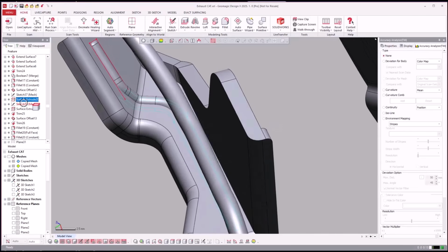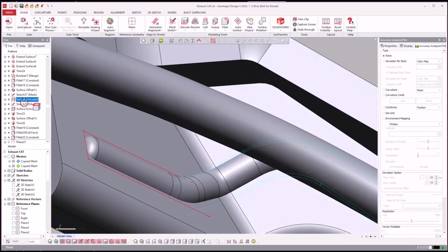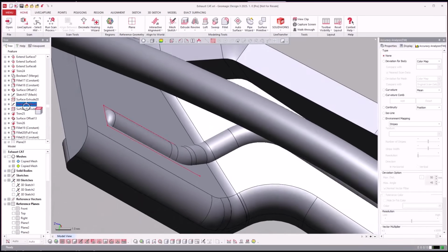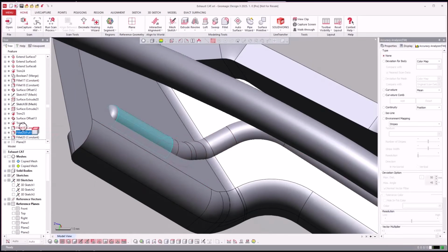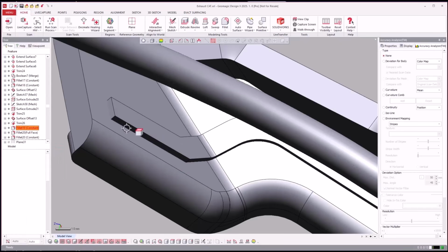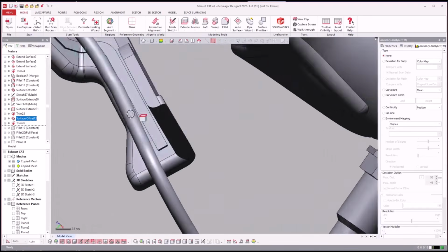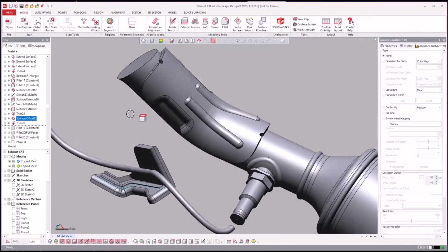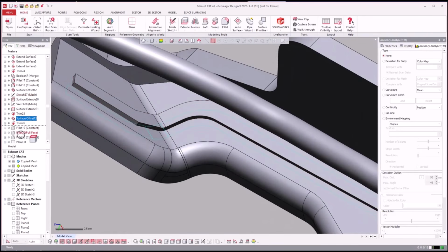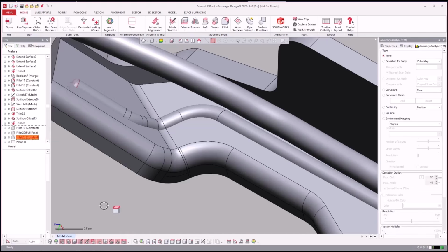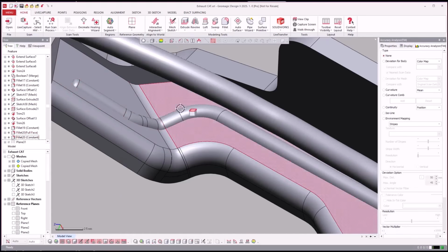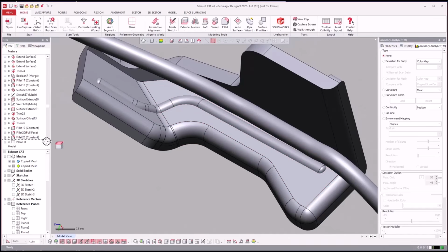Yeah, it looks like they designed it in a couple of pieces instead of doing it as a sweep. They designed this right here. Let's just roll right back because I'm just curious. Yep. Okay, so they just did a surface offset for that piece that they drew, and then went ahead and filleted it all. Boom. When you first see it, you're like, hey, I could do a sweep, but that must have been faster for him, just drawing that out versus going the other direction with it.